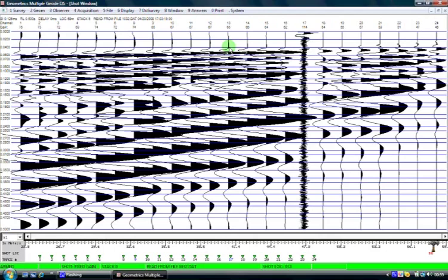In a seismic refraction data acquisition sequence, it is important that we locate the time for our first breaks as accurately as possible, because it's only by achieving high accuracy in this travel time that we get the best fidelity in our data analysis. As we're displaying a very long record length at the moment, 1/2 a second, and our travel times are only of the order of 0.05 of a second, probably what we need to do is expand our record.